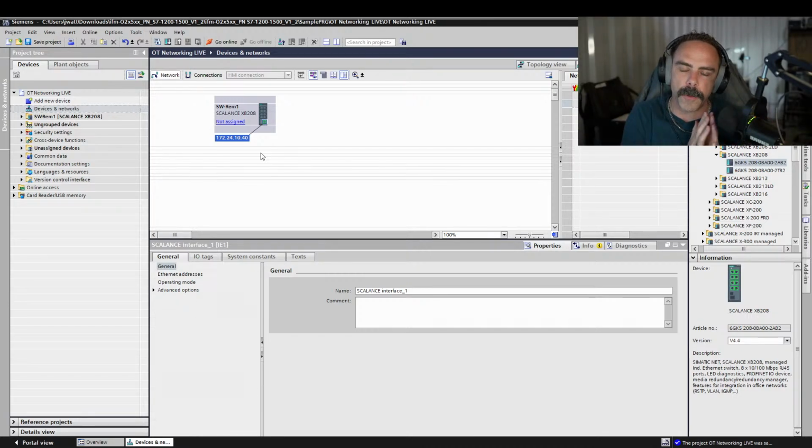Then all of a sudden we can put all of our PLC hardware, all of our remote racks, all of our drives, all of that on one full 255 subnet range, and then have all of the networking components have a 255 host range on that other one. So that's something we can do.